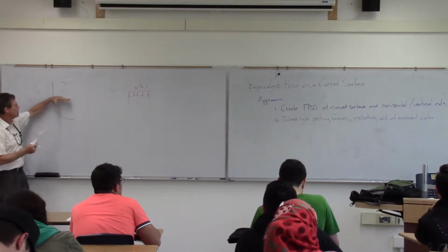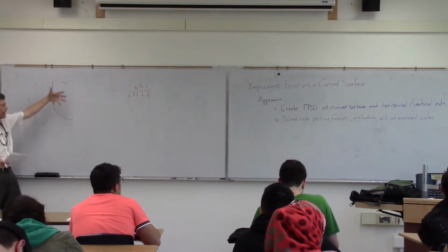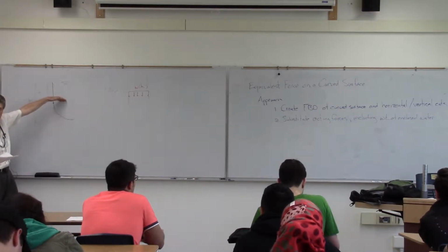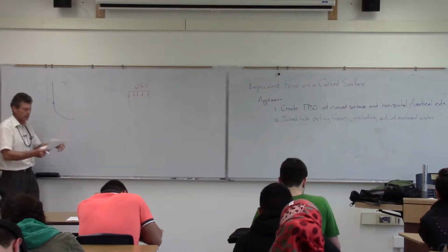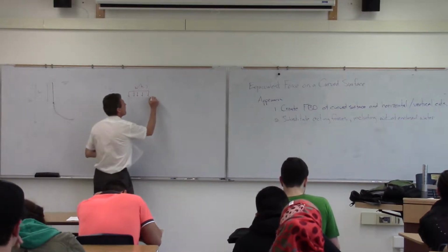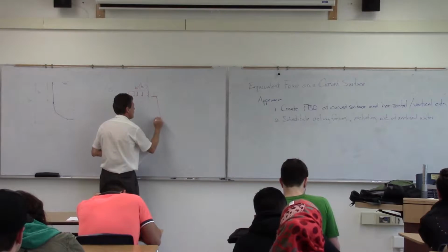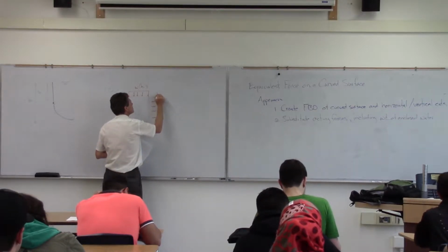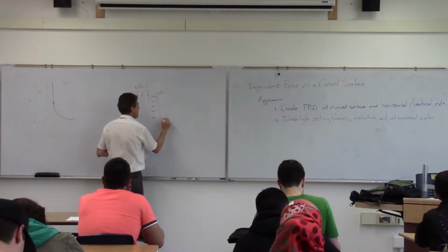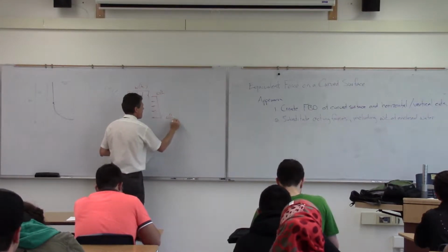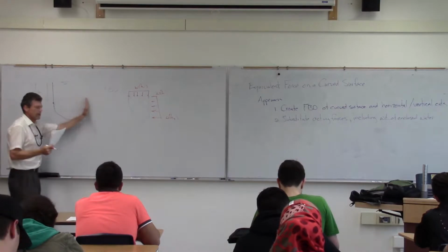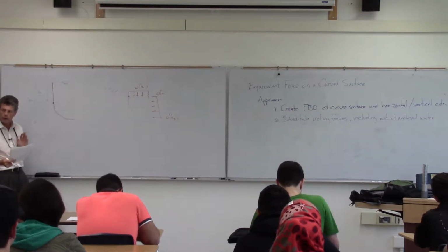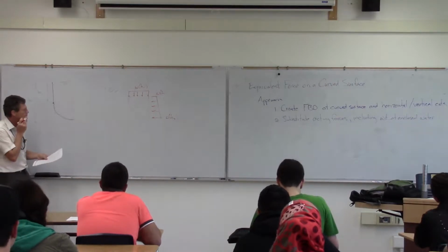So I've taken that portion of the water away, but I have to substitute in, like we do in equilibrium, that set of forces that are acting there. Same thing with the vertical cut, except now it will have that linear aspect like so. But again, we've taken all this water away here, and this is what that water is doing to this hunk of water here. So we've substituted that force in.